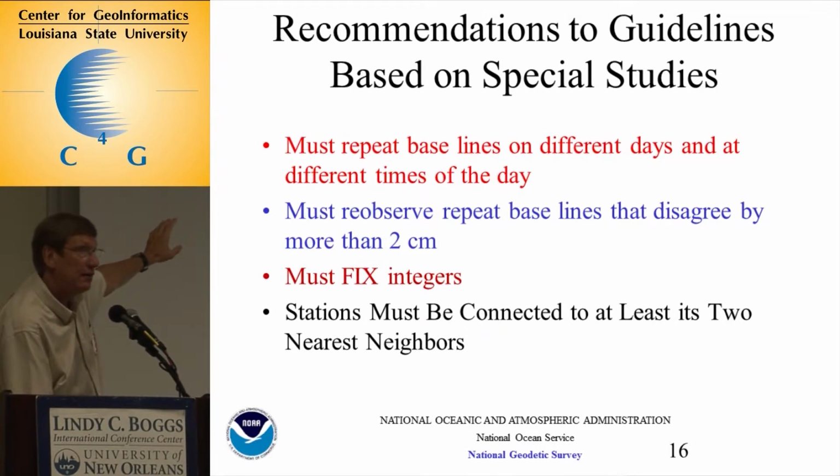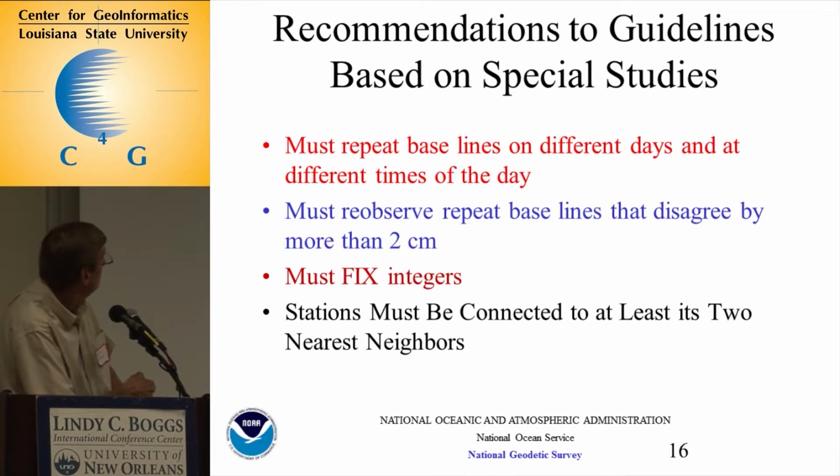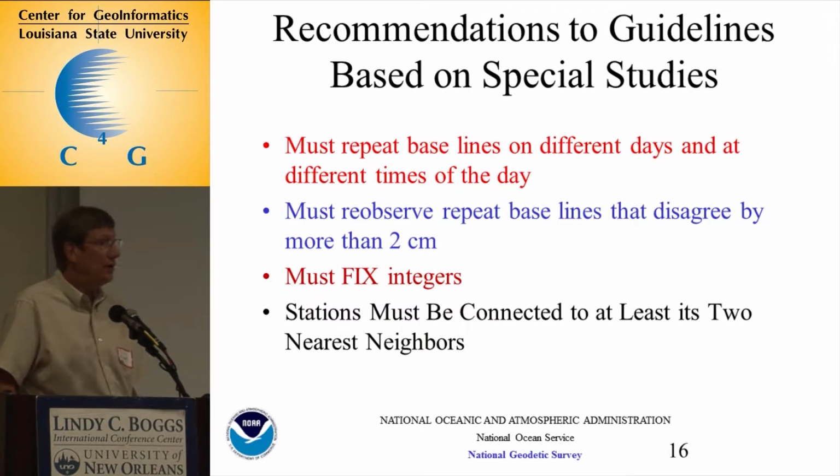So this is based on the guidelines, what we were looking at. You must repeat the baselines on different days and at different times of the day. Very, very important, very critical. You have to reobserve baselines that disagree by 2 centimeters. If you're trying to get something better than a couple centimeters, and you do it on different days and you still don't get that check, then you have to reobserve it.